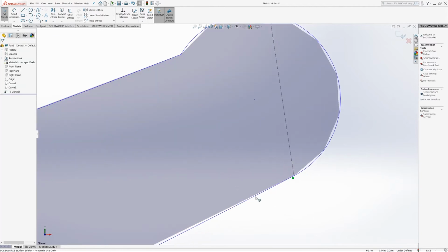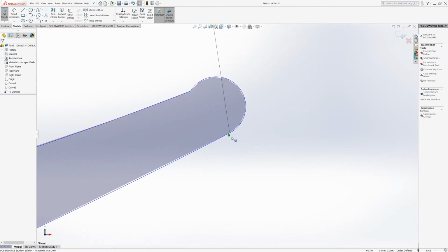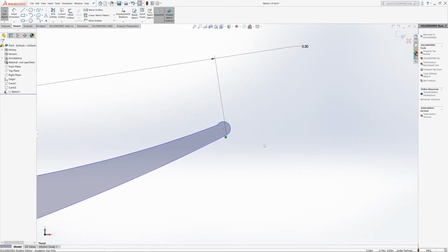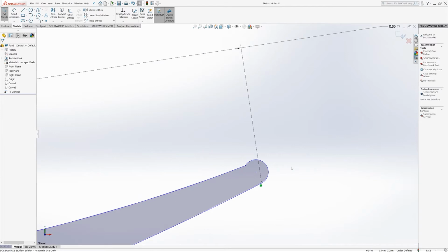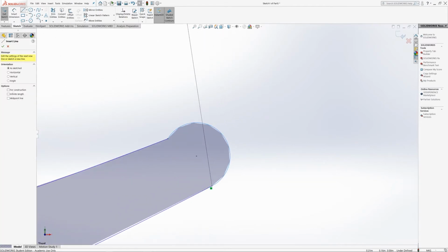The crucial thing is you've got the tangent on this bottom edge. This lower edge is important. That's where we're going to be getting most of our downfalls from. So just make sure the tangent is on the bottom edge and the bottom edge is smooth. Okay. So yeah, as we did at the front, we're going to add some tangents to that trailing edge.